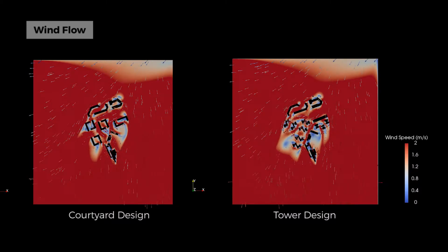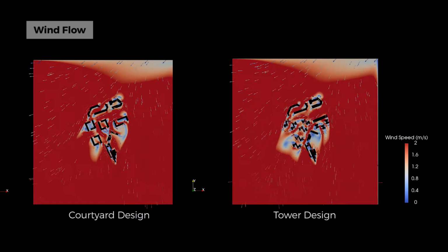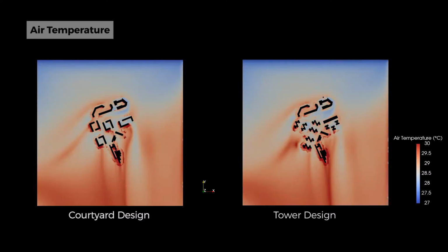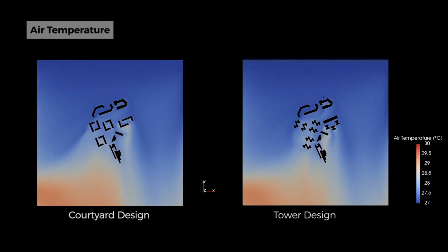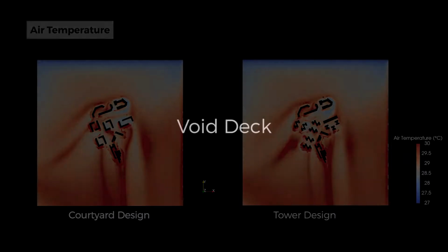According to the ventilation simulation, wind channels in between the buildings are cooler zones as compared to the backside of buildings. In regions where ventilation is better and enhanced, convection of accumulated heat will experience lower air temperature up to 2 degrees Celsius.